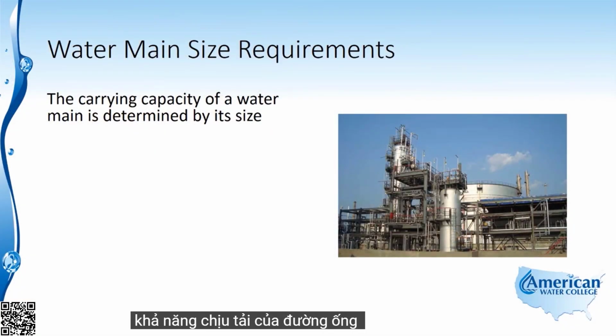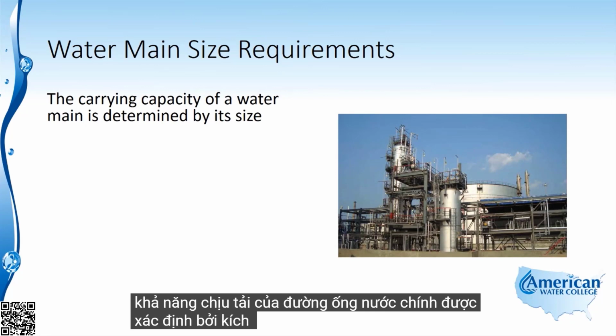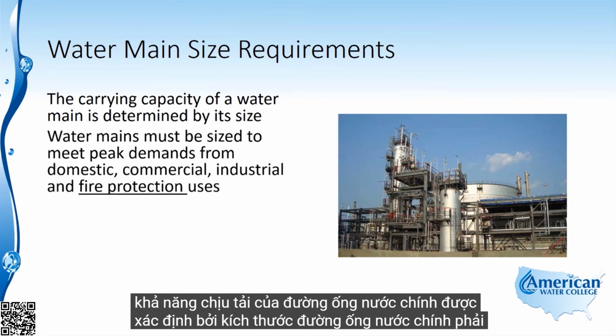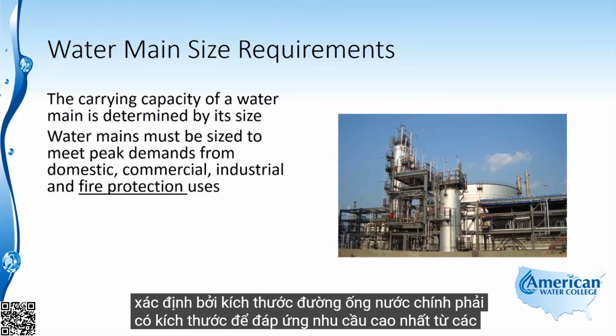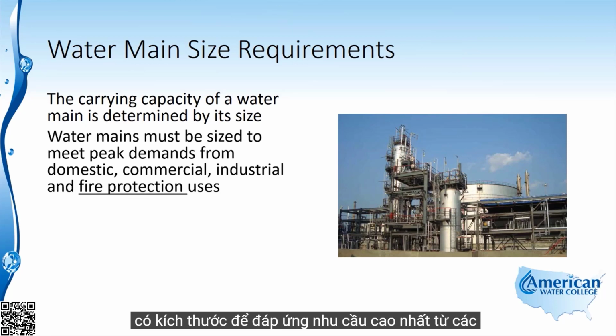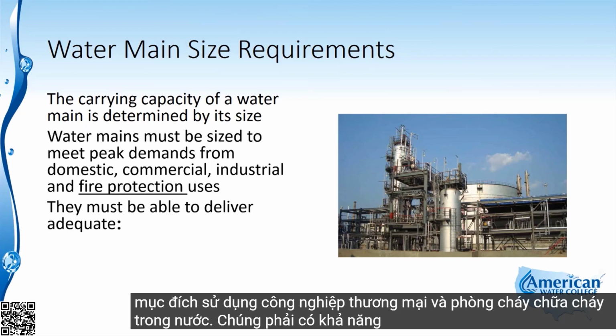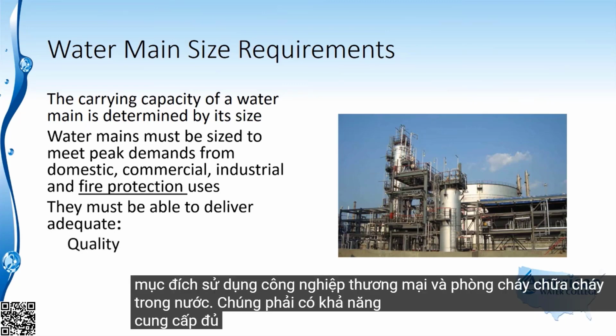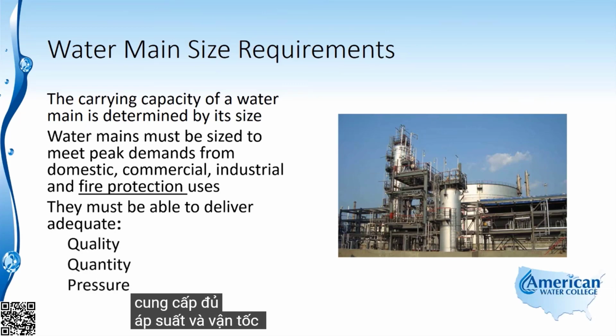The carrying capacity of a water main is determined by its size. Water mains must be sized to meet peak demands from domestic, commercial, industrial, and fire protection uses. They must be able to deliver adequate quality, quantity, pressure, and velocity.